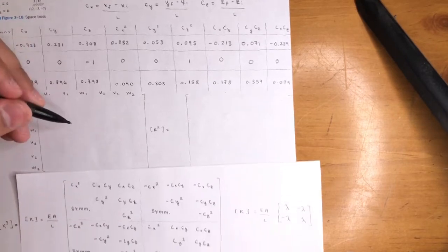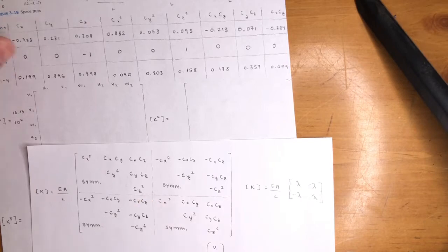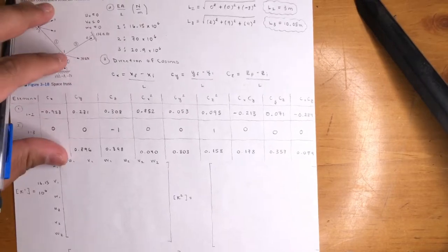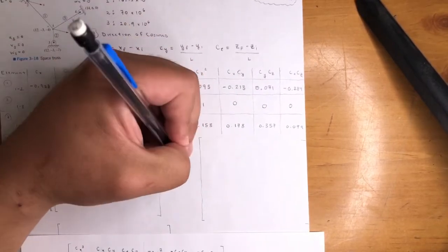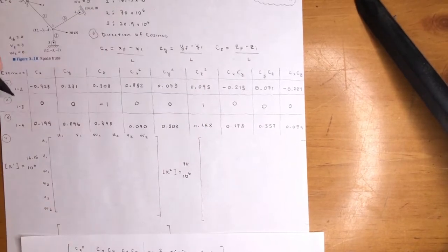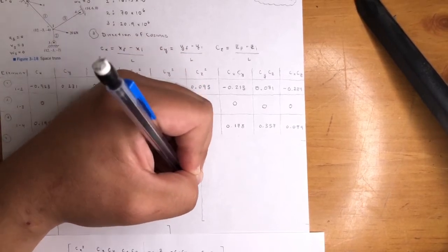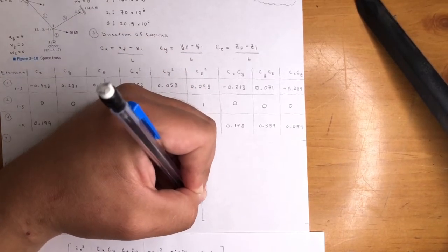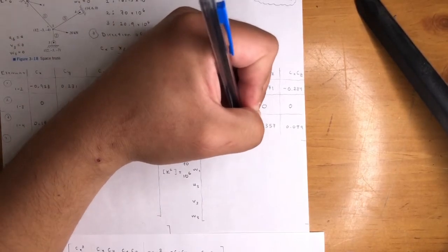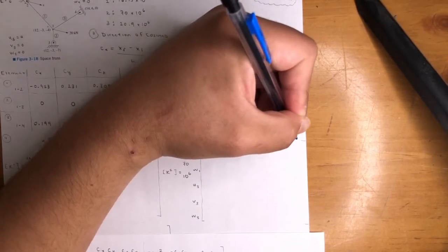We could go ahead and fill in this table, right, if we really wanted to. We already have all our CX, CYs, whatever, and we just plug in the table right there. But let's go ahead and continue doing the next element. For element 2, stiffness is 70 times 10 to the 6, as we determined, right? 70 times 10 to the 6, and that is between nodes 1 and 3. So we're going to go U1, V1, W1, U3, V3, W3. Same thing across, U1, V1, W1, U3, V3, W3.